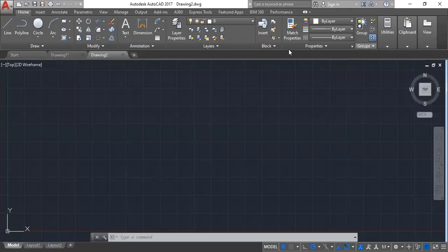I would like to explain what we call layers, line types, and also the line weight. Now, in this application, more so when you're working on a complex project that has different things, for example, a house you're drawing. A house has a foundation, walls, slabs, windows, and doors. All those different things are supposed to be placed on different layers.